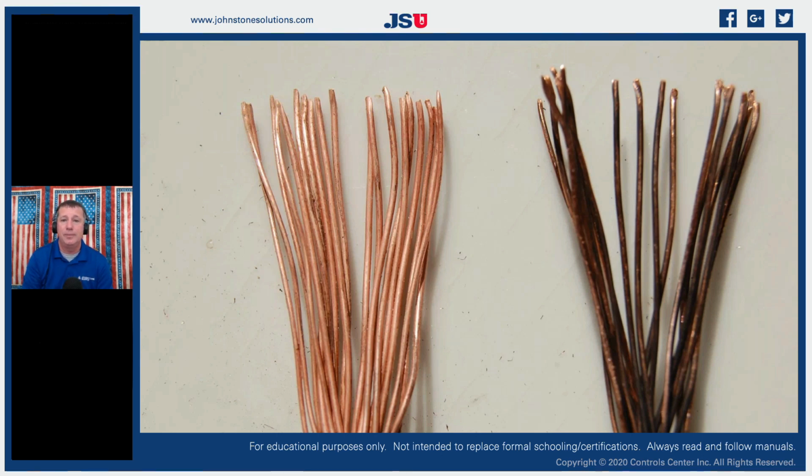and with that corrosion. So we're finding that installations where we have taken out legacy style 24-volt AC operated units and we've put in communicating systems and reused the existing control wire, that control wire may have worked fine on legacy with some of that extra patina and corrosion, but does not function properly for communication.